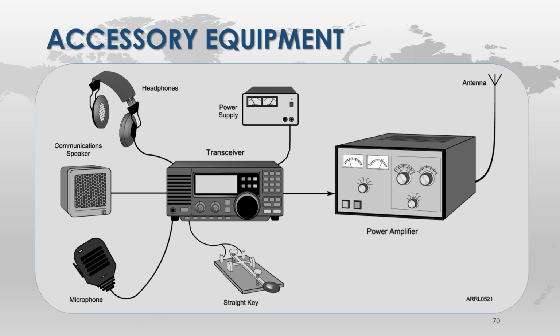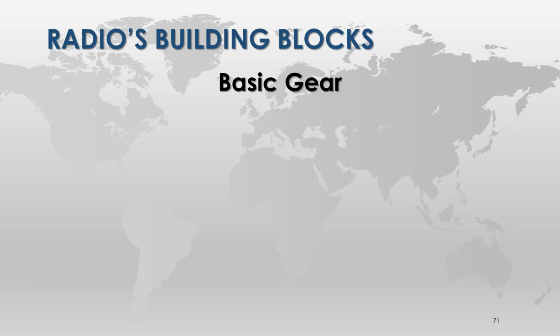I do have an amplifier. I can take my radio and plug 5 watts into it, throw it through the amplifier and get 65 watts out on single sideband. Well, 65 watts is more than my radio will spit out, so that's the reason to have it, and that will get me up further distance on single sideband. And I have the added advantage of my expensive radio only running 5 watts, which is easier on my radio. Less heat, I can talk a lot more, and as a recovering politician, I need that.